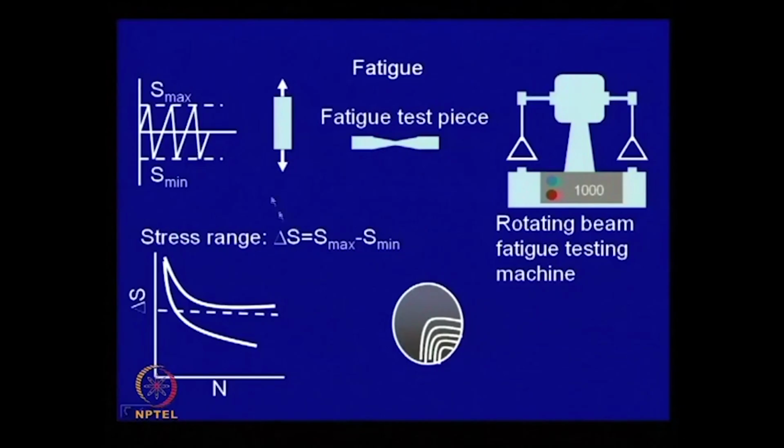Similarly, think about a wheel or rail of a car or of a railway carriage. Basically these components are subjected to cyclic loading. Stress at a point keeps on varying, it is not subjected to a constant stress, which is pictorially shown over here. So, any component, the stress keeps on fluctuating something like this, it goes to a maximum stress, then goes to a minimum stress. It can be tension, compression, and diagrammatically it is shown here.